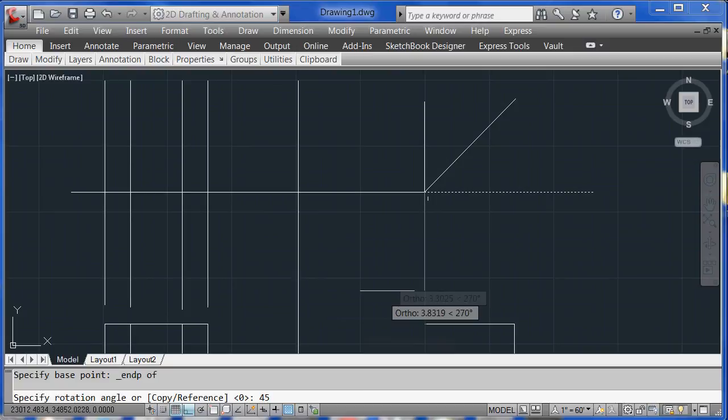So I can just erase those. Erase that one. E for erase. Now I'm going to trim. I'm going to trim all these in one bunch. Okay. I'm going to start out here and swoop, and then I'm just going to hit return because I'm done with my selection of the cutting lines, and I'm just going to start cutting them individually here like this, like that, like that, like that. There, there, there, there, and these two. Okay. Notice, and I'm almost there.